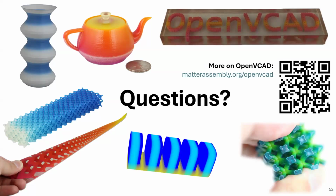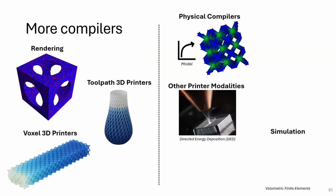Well, explain the directed energy deposition. Yeah. So there's various flavors of DED, is what it's called. The ones that I'm talking about right now have some kind of powder they bring in. They lay that powder down and they'll use some kind of directed energy. So they can be lasers. Usually these things are printed in completely inert environments, so we'll print them in like a vacuum chamber or something like that. They'll fire it and they'll fuse those metal powders together and then stack them up layer by layer.